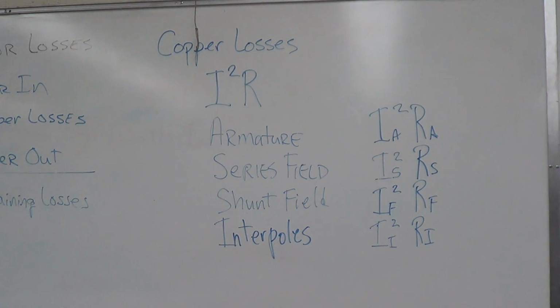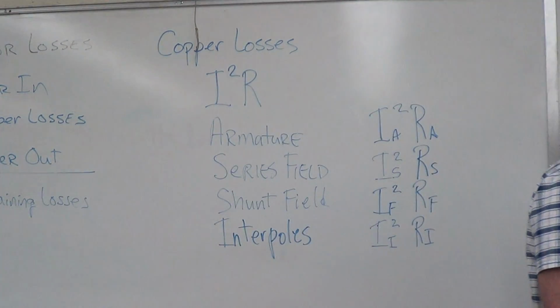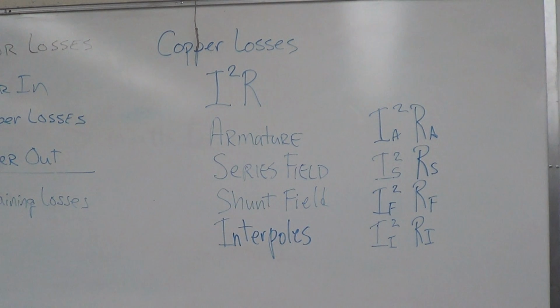Right. And hopefully, if the motor is efficient, their contribution will be a very small part of your losses. You're going to find that our copper losses should be a large contribution to what we're measuring.